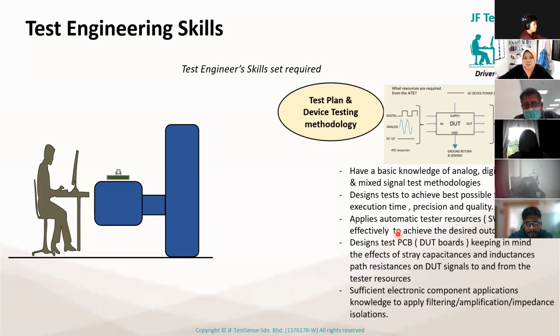Sometimes you need a buffer to buffer the high impedance output of a device when it sends a signal to the tester. Or the other way around, when a tester sends a signal to the device, you probably need a filter to filter out other frequency components.